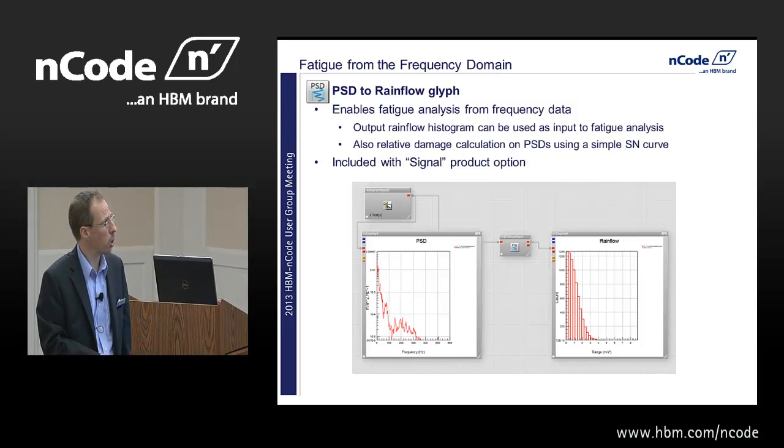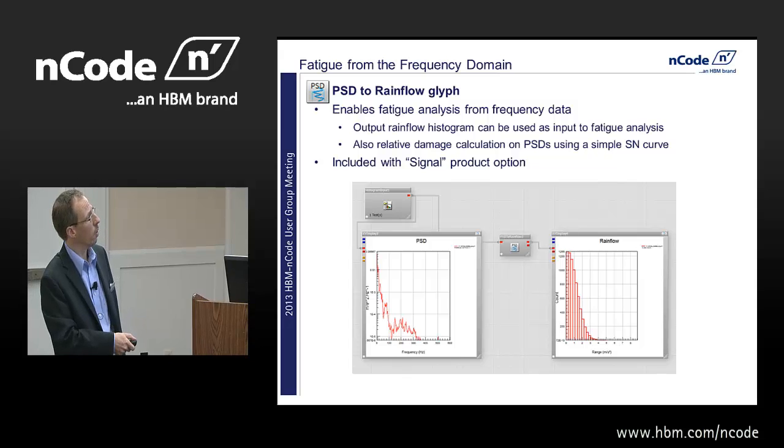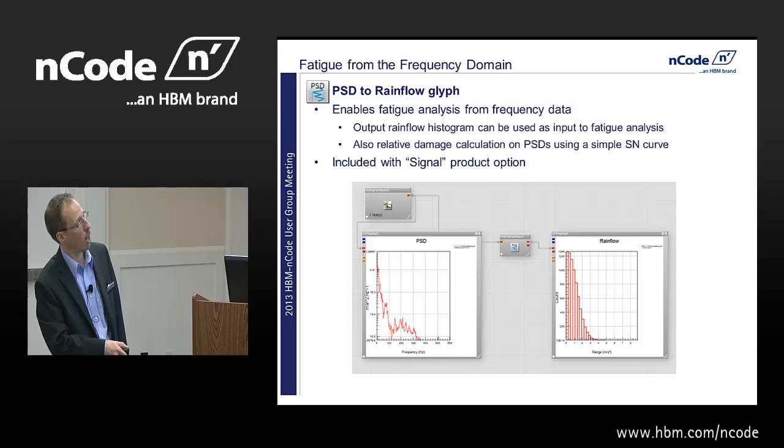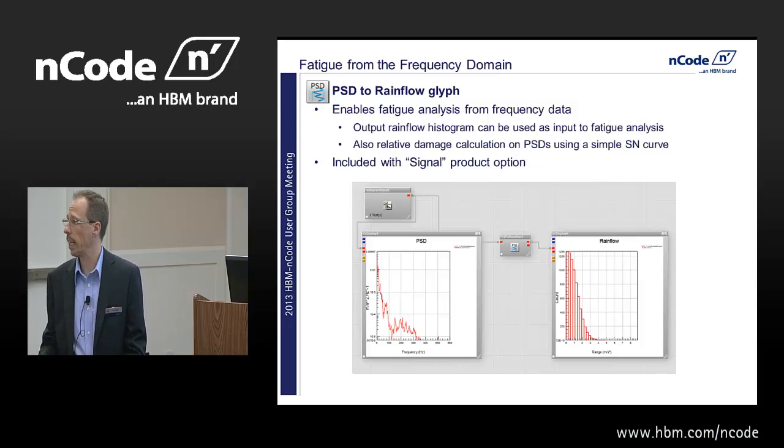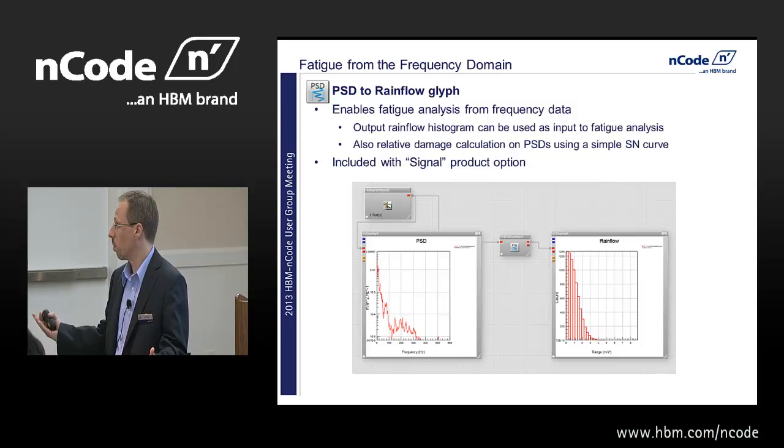Well, this glyph enables you to go from a PSD in the frequency domain to a rainflow cycle count. So how many cycles do you have of what size? And then you can feed that directly into the regular fatigue analysis glyphs.